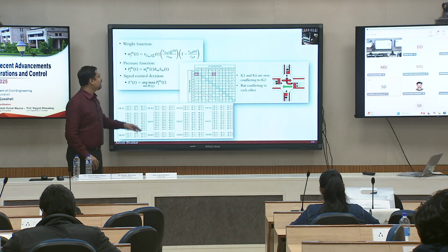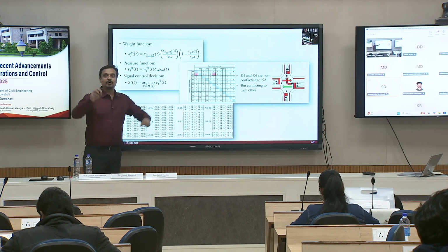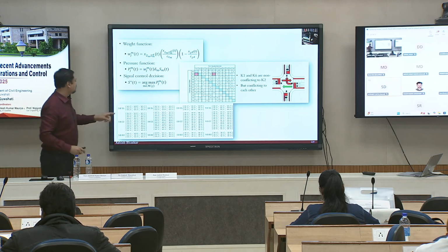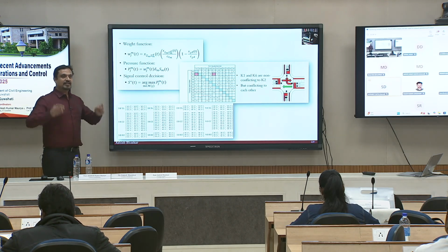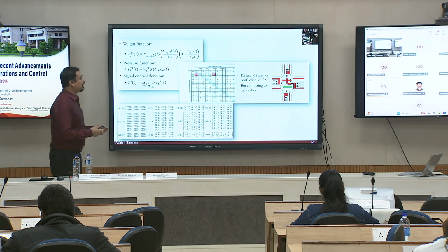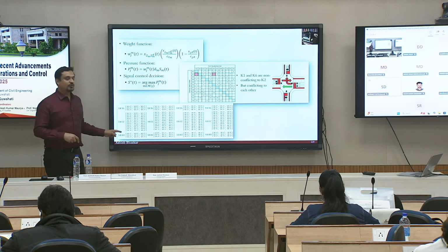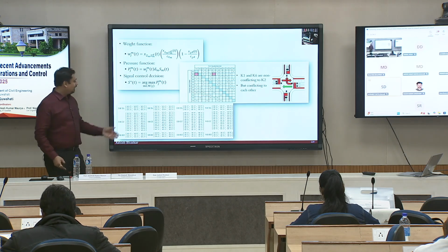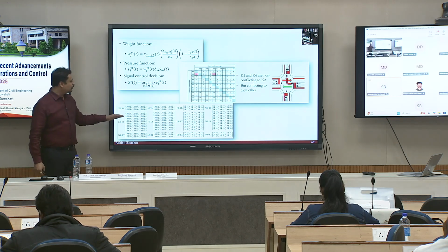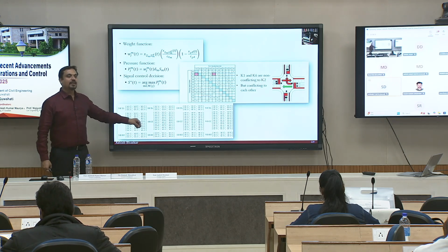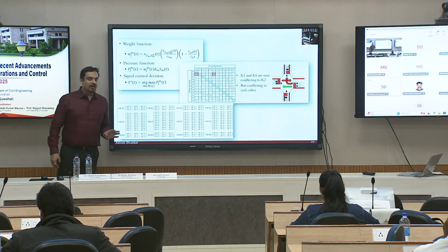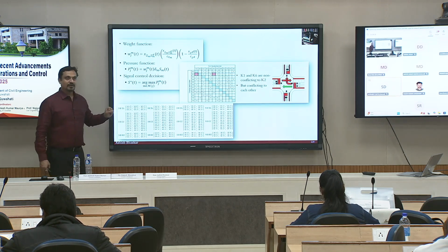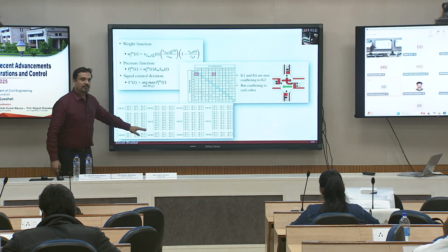So his algorithm is saying that I have a function where I'm going to select a specific approach based on some values. And I make my decision, I'm going to select, let's say, northbound left. So that is my decision to select northbound left. But then I'm also going to check, I'm not just going to run northbound left. I'm going to run other approaches also, which are compatible with it. But I have a pool to select. I'm going to select the one which is having, let's say, the maximum amount of expected queue length or delay or whatever it is, right? I will select one from there and I will let it run with that.